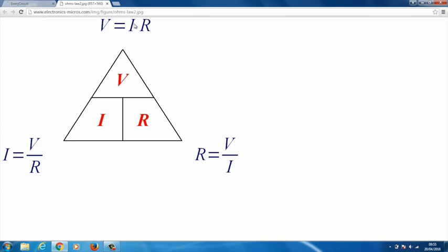If we go and have a look at our Ohm's law triangle, then we know 2 values now. We know current and we know the voltage. The voltage is 2 volts and the current is 20 milliamps. So we're looking at this equation here. Resistance is equal to 2 volts over 0.02 amps. So we always write the current in amps in our equation.